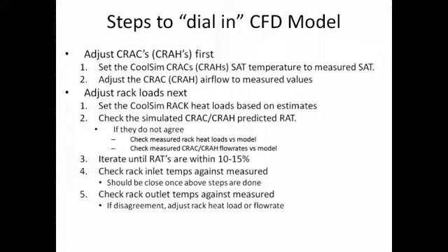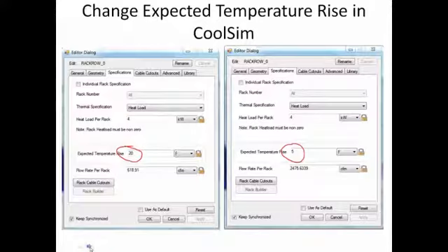And when we calculate an average, it's an average across that 1,000 set of points on a given inlet or outlet. When you're using sensors, it's not the case. You can't afford to put 1,000 there. So please understand that the simulated and measured will always vary a little bit, just simply based on the way they're doing sampling and they're doing calculation.